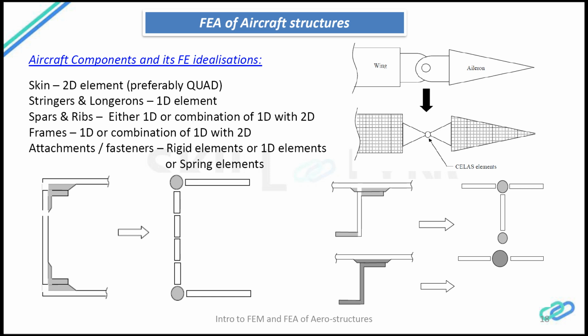And finally, the interface points. The FE analyst in the aerospace sector should really have the capability to understand the connection points, which are the interface points, where and how the structure is attached, and how to model the connection points within the FEM.